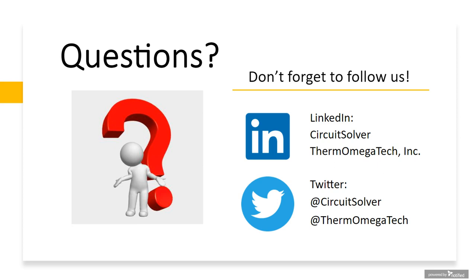There's a slide that says CSUSF. What does that refer to at the end of the branch line on the hot water supply? I believe Tom mentioned it in the presentation too. It is a balancing valve, a thermostatic balancing valve in particular. That's one of our brands once again. So that just has the capability of balancing at a lower temperature, typically like 120 degrees, whatever your normal everyday temperature would be, and then also your high temperature for your Legionella flushes, your disinfection flushes at 170 or 160 degrees.